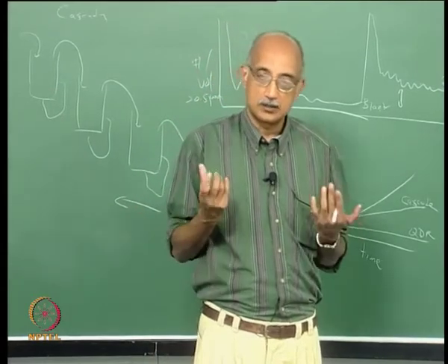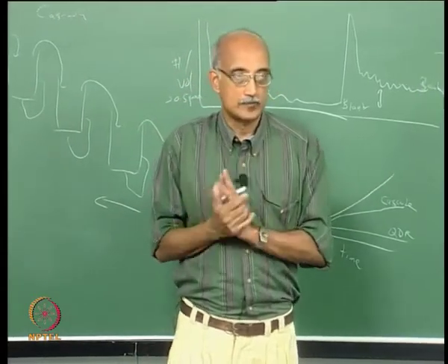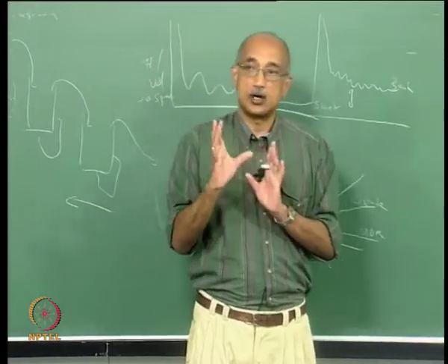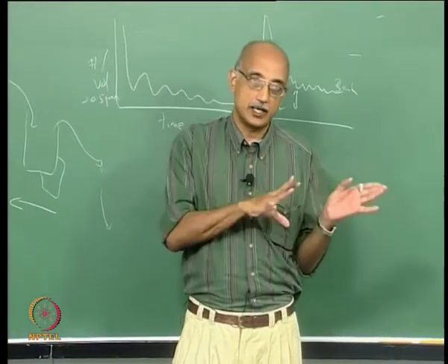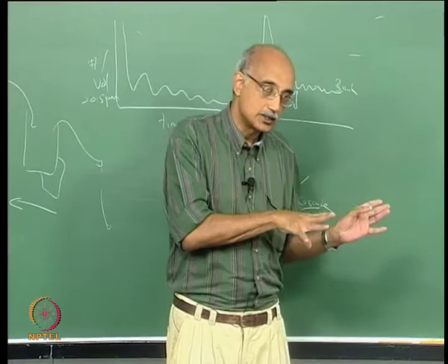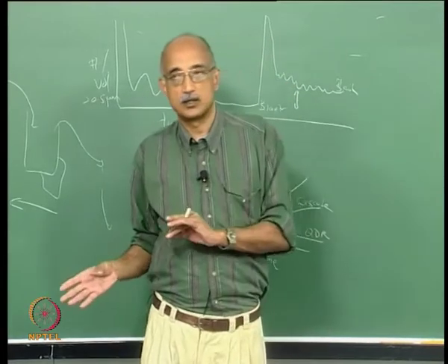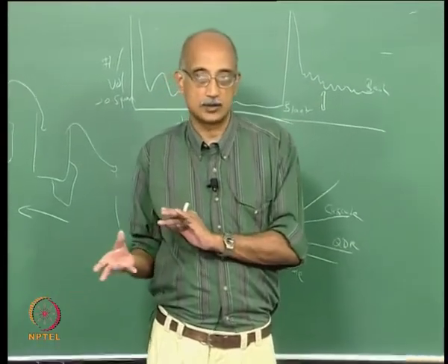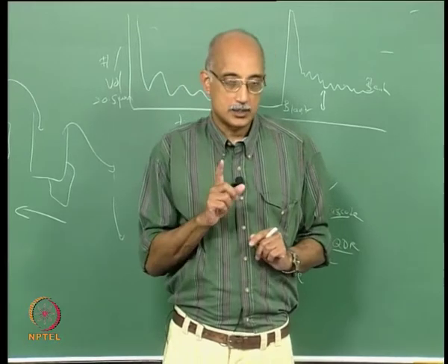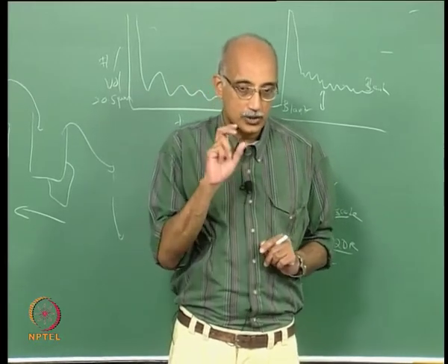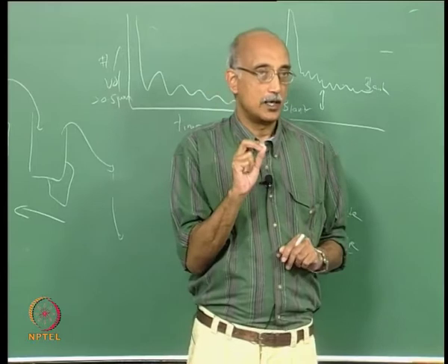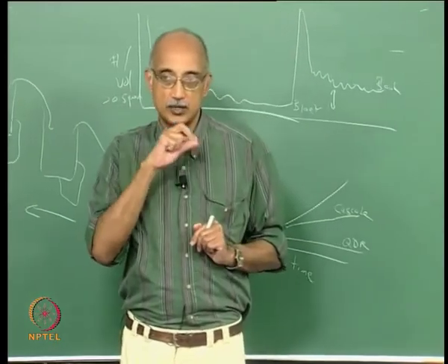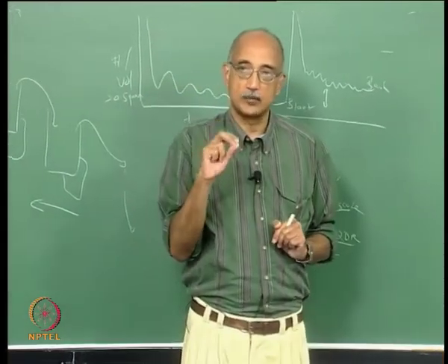Interestingly, you can take the same reactor and by slightly altering its operating conditions, you can make it behave either like a particle synthesis reactor or as a thin film deposition reactor. In a thin film deposition reactor, you have to make sure that particles do not form. And if you remember our discussion from nanoparticle synthesis, particles can form by two mechanisms.